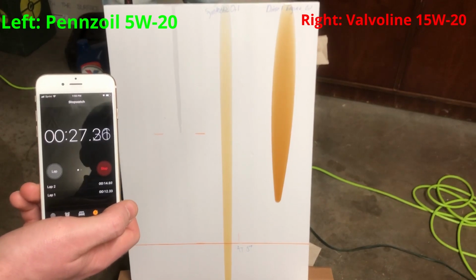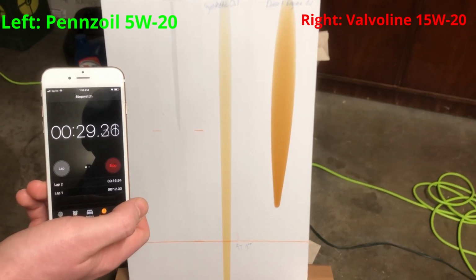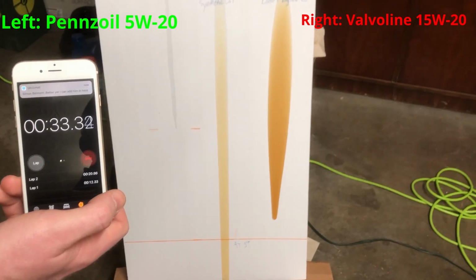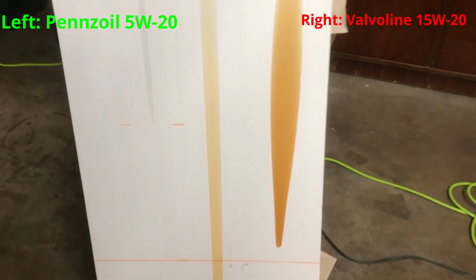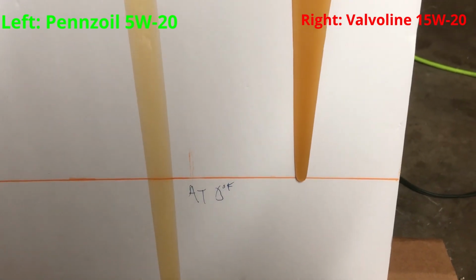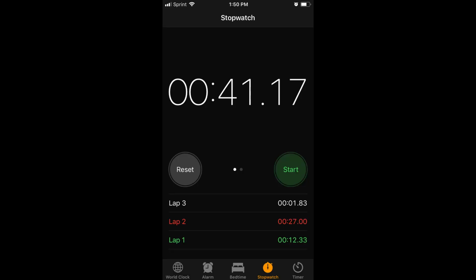This experiment concluded a couple things about the oils used. The synthetic oil 5W-20 performed better in cold conditions because of the 5W standards it was rated for. Although the 15W oil did not perform well in the cold, we can conclude that in warmer conditions the diesel engine oil would perform better and not thin out as quickly as possibly the 5W-20 oil because of its high temperature rating of 40. This concludes our project.